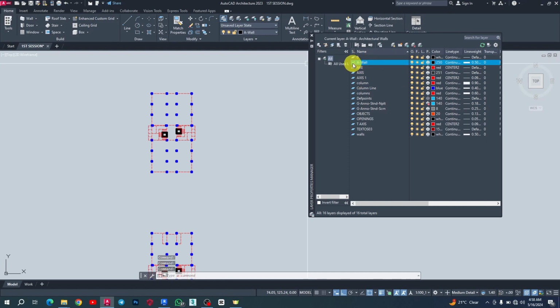To choose a particular axis, you don't have to double click on it. There is a check mark by the side here that tells you that is the axis in use, and up here you also see it. So I want to freeze this terrain axis, this one down here. The red one is the one that is in use here. So I come down to this icon here, and you see it, you freeze it. When I click on it, everything in that layer automatically disappears.